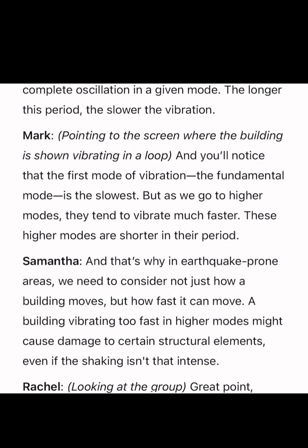That means it takes more time, so the natural period will be longest for the first mode. It moves in the slowest way. But as we go to the higher modes, they tend to vibrate much faster. These higher modes are shorter in their period, so they vibrate faster.